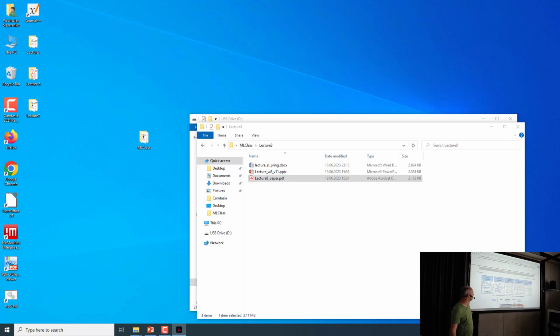They trained a simple model to output one value that they call the health index. Depending on the health index, your engine is either operating well or not so well. Then they trained a degradation model using this bidirectional RNN in order to predict the remaining useful life based on the previous measurements.